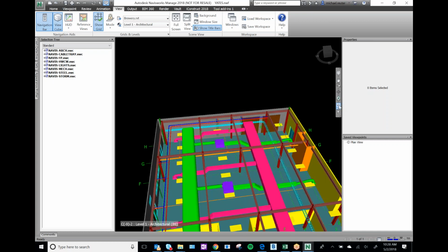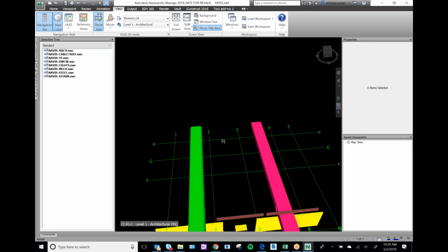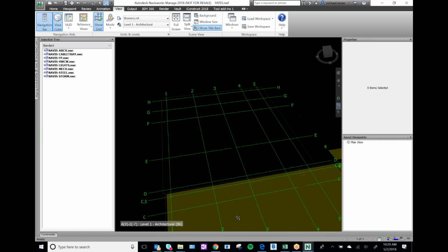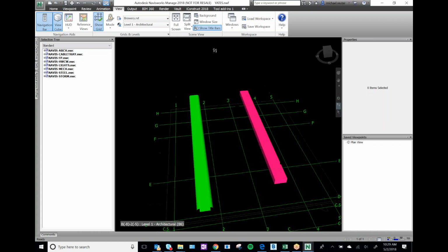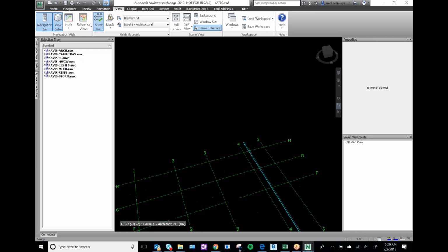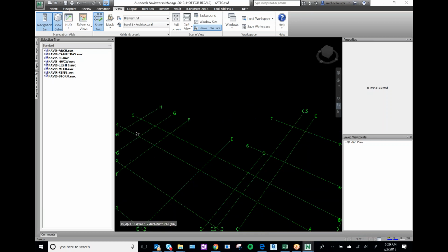Right. Next, we've got the walk tool. I call this the feet. I typically use the hands and the feet. That's pretty much all that I ever use. I don't even mess with these ones in between because these do everything. So the walk tool works completely different than all the other ones. Basically, you left click on your mouse and then you drag. When you do that, you can see it's kind of walking. The further away from center of screen I go, the faster it's going to walk. I can turn, so think of it like the center of your screen is kind of like a crosshair. So if I want to look left, then I can do that.